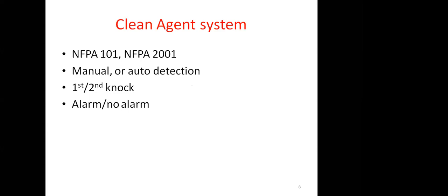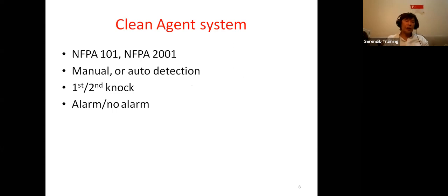Yeah, sure. Mohammed, actually, when we are connecting duct detectors to the AHU, is that to be monitored as a supervisory or to be triggered as an alarm? It functions just like any other detector. If it's activated, it will create an alarm in the fire panel, but it doesn't activate the general alarm of the building. It doesn't require evacuation of the building. If the smoke duct detector is faulty, short-circuited, open-circuited, or removed for whatever reason, it becomes a supervisory or trouble signal to the fire alarm panel.